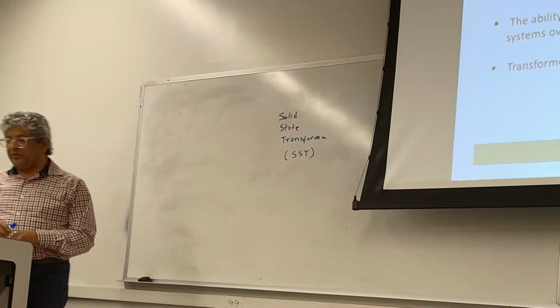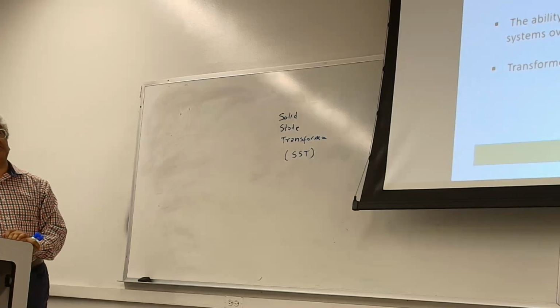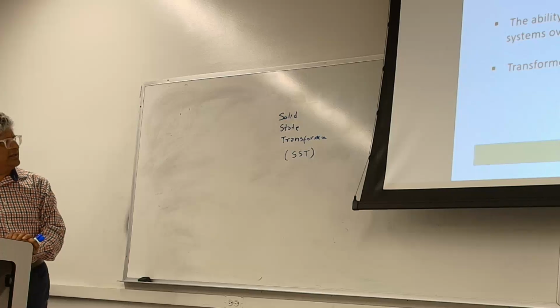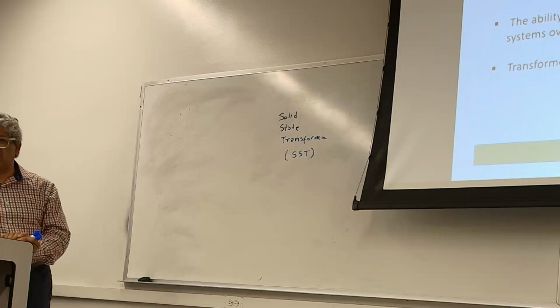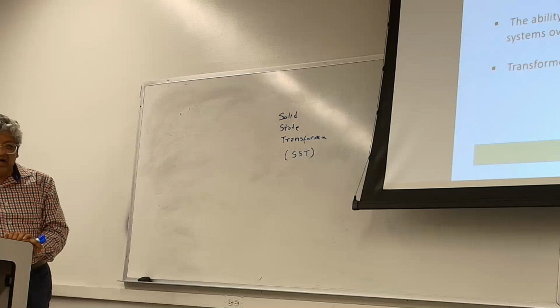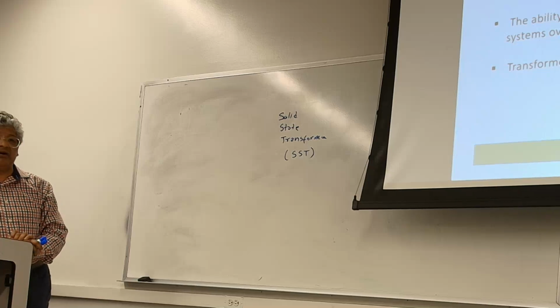So what the Department of Energy has been wanting to do, once again, they were pushing, the last administration, actually it started with the Obama administration, was to ask, are there other things that we can do if we were to utilize power electronics and have transformers that have the ability to push power in both directions, what we call bidirectional power flow? Can you control power factor? Can you correct harmonics? There's a lot of other things. Can you mitigate sags and swells, whatever type of power quality issues that we encounter in the system?